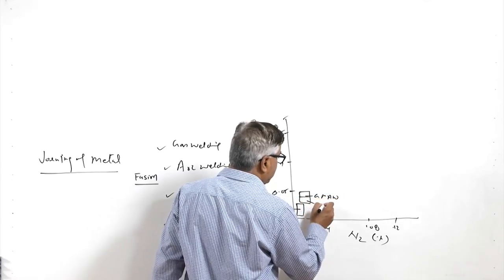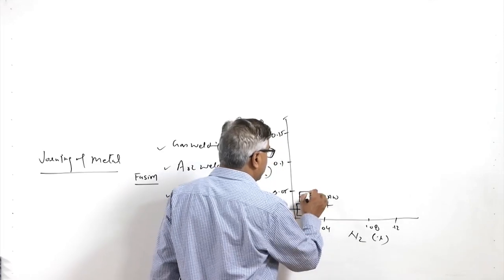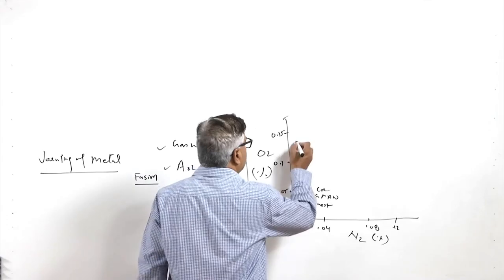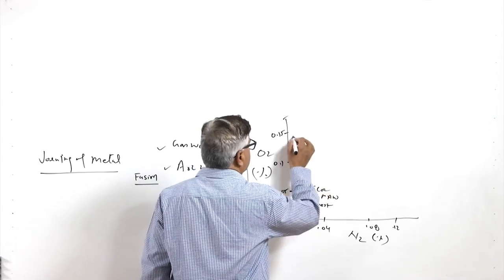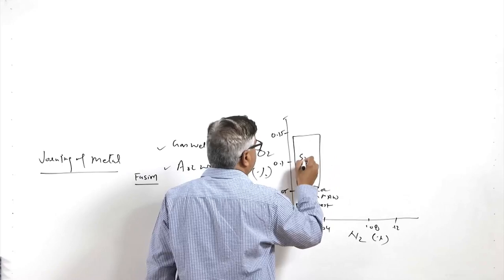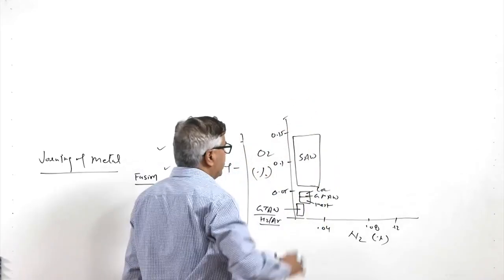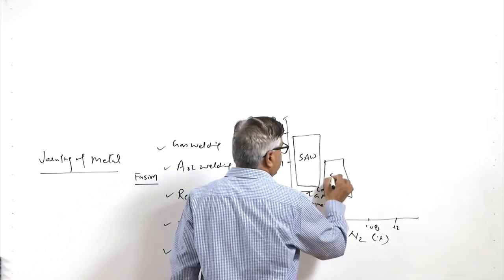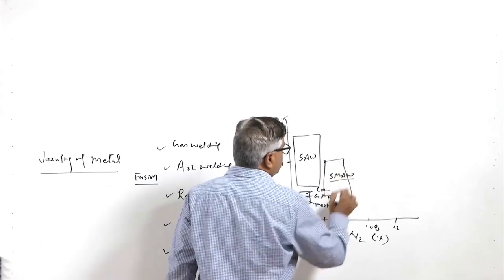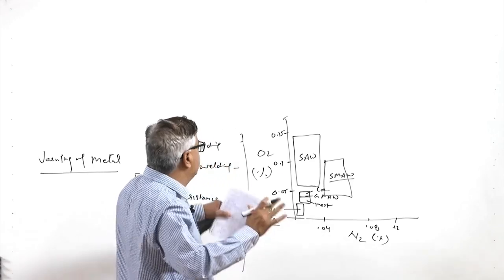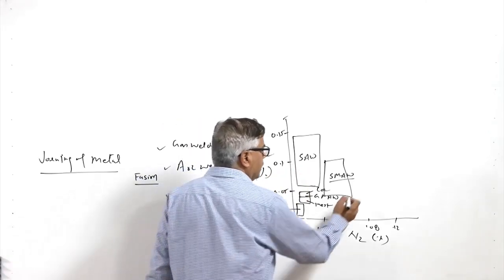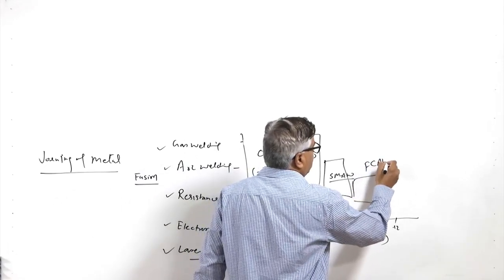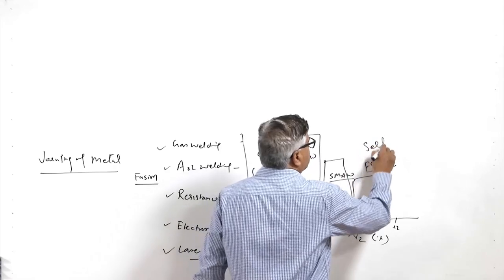It will result in somewhat lower oxygen, and with CO2 more oxygen in the weld is produced. Then we have processes like submerged arc welding, and the shielded metal arc welding process, which is the stick electrode process, which will result in more oxygen as well as nitrogen, and a large amount of oxygen and nitrogen is produced in processes like FCAW, flux cored arc welding, or self shielded